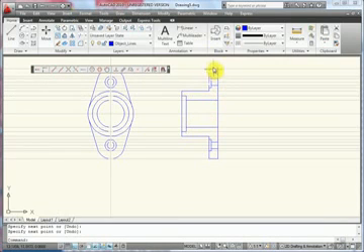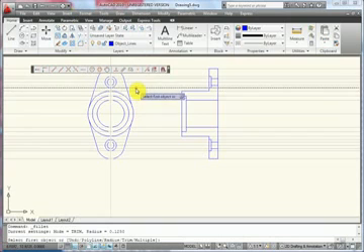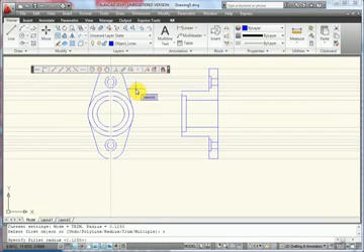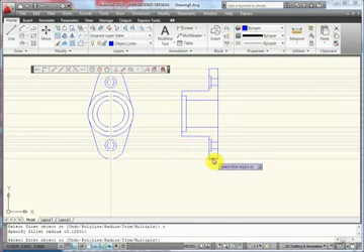One last thing is we want to put a 1/8 inch radius or fillet on the corner of this part. So we're going to use the fillet tool. Input R on the keyboard with a radius of 0.125. Spacebar. Now that we have the pick box, we can just select the two edges we want, and I'll put a radius on it.